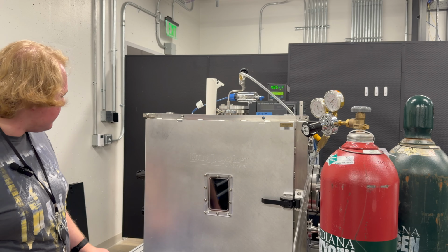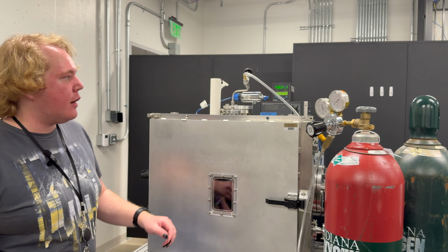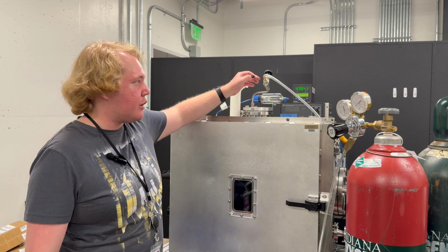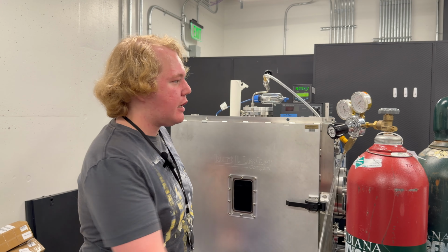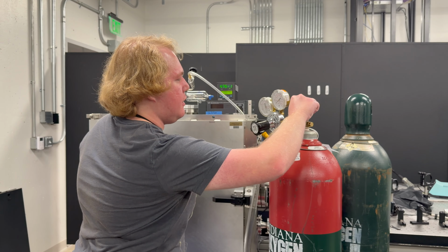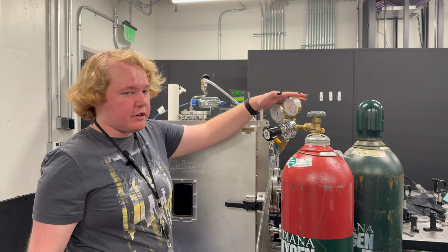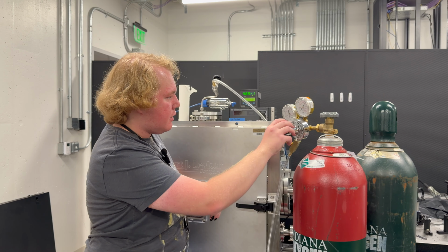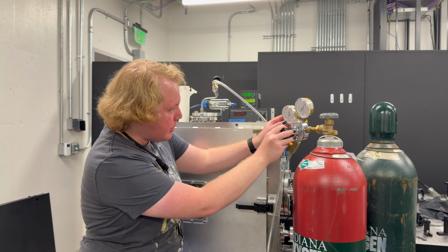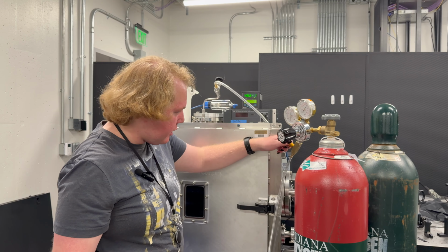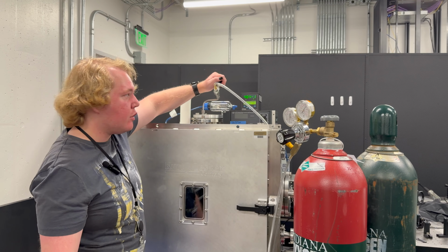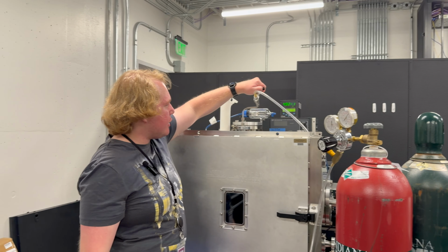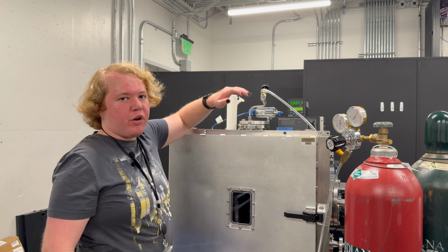But for now, we can leave the roughing pump on, and then considering that this would have been evacuated and brought back to this pressure, we can use the test gas that we're using here, which is nitrogen in this case. Obviously, they are all attached with pressure regulators to ensure safe operation. We raise the pressure slightly above atmospheric and have a flow controller here as well as a needle valve. And through these, we're able to monitor the pressure and regulate it until it is approximately stable.